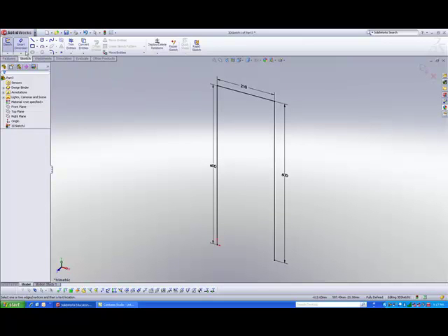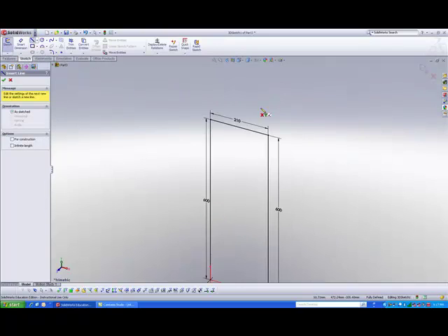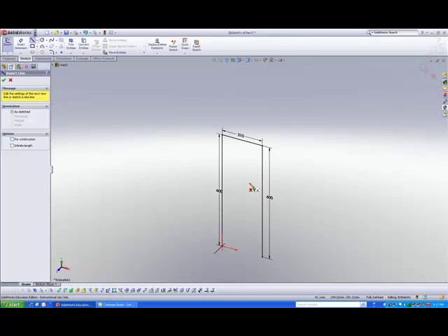So we are not done yet. We can continue with our 3D sketch. Because we have not exited from the sketch environment, we are able to continue to click on the line tool and continue sketching our 3D sketch. This time round, I'm going to sketch on the YZ plane. So just press tab.